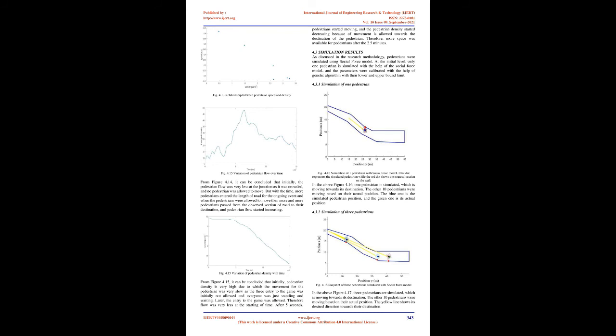The speed variation diagram is also plotted, in which the variation of average speed along the length of travel is shown. Moreover, there are a lot of pedestrian trajectories which were plotted. Trajectory data is an important source of information like speed, flow, and density, which are macroscopic characteristics.